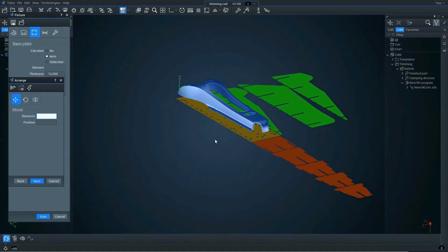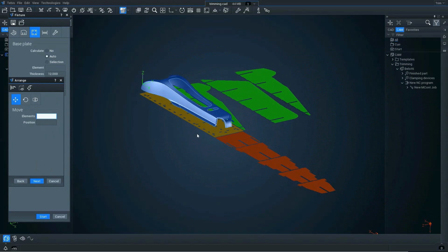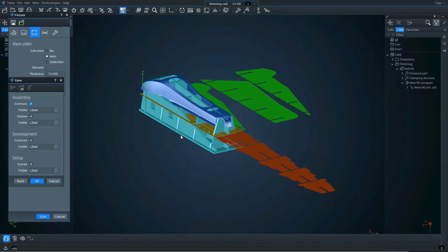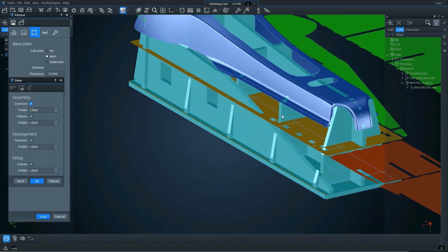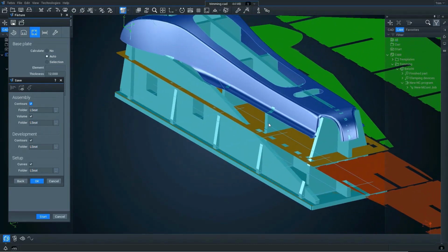Then what we get is a basic layout. This will allow us to lay a sheet of MDF in the machine and basically just cut the fixture out, ready for manufacturing. The next operation then will flesh the fixture and give us a full 3D version of the fixture, which allows us to use this in the programming process. So as an alternative to the full form fixture that we saw with programming, we can actually use this lattice fixture instead.